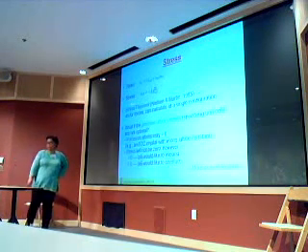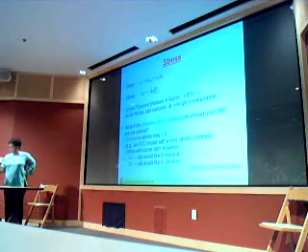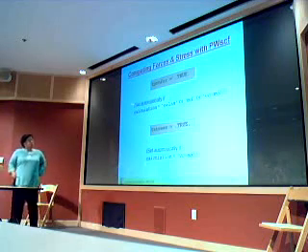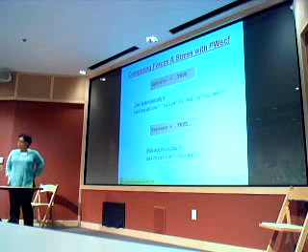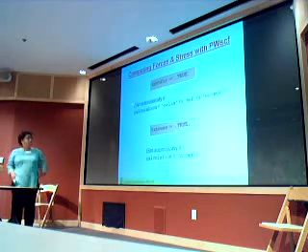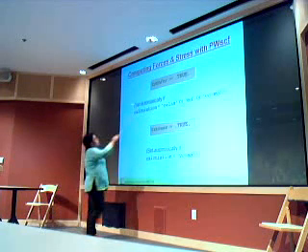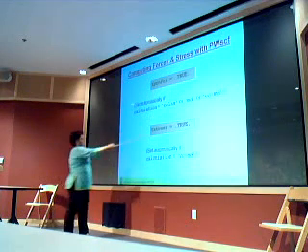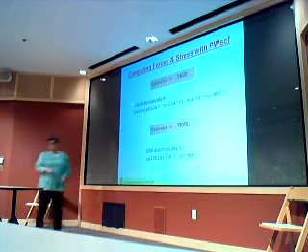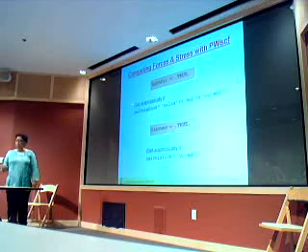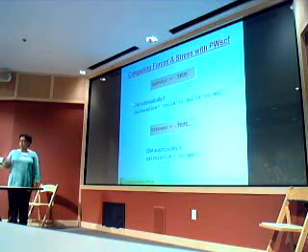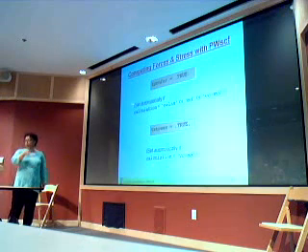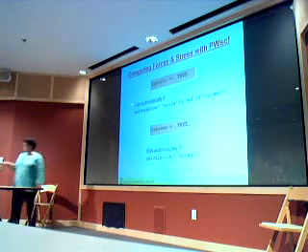So you can use the stress tensor to optimize the cell size, and Stefano de Gironcoli will talk about it in the next talk. So when you're running PWSCF, if you want to compute forces and stresses, you just have to turn these flags on. So this is to say whether you should print forces, and you have to make that true, and this is whether to compute stress. And if you are doing a calculation where you're going to relax the ionic positions or molecular dynamics, where you obviously need forces, then you don't need to bother to set it on.